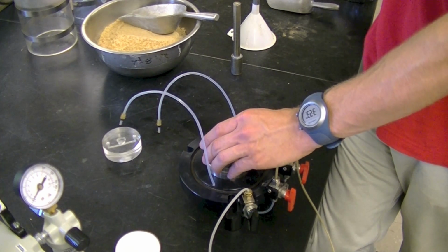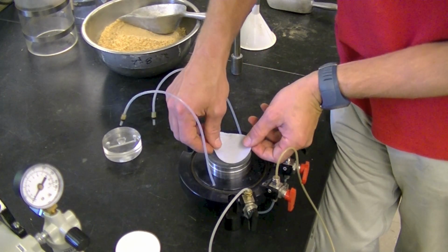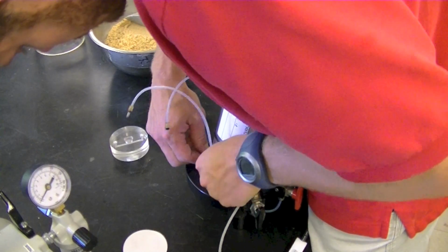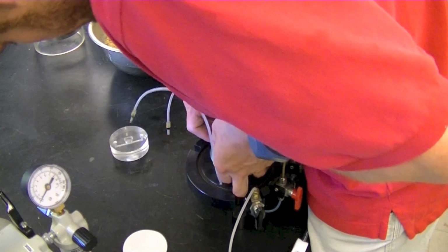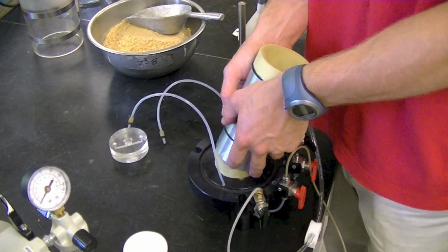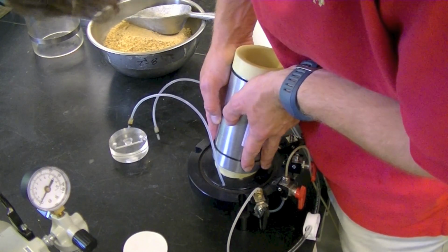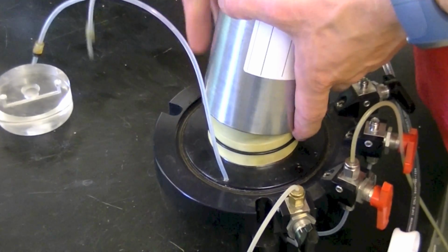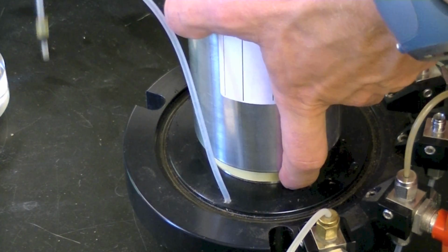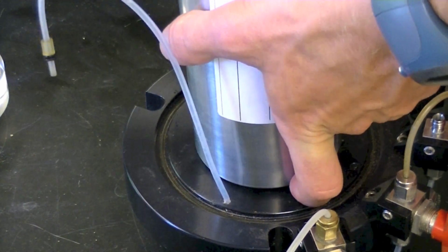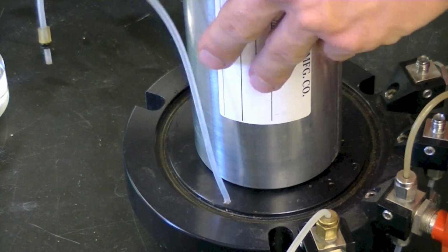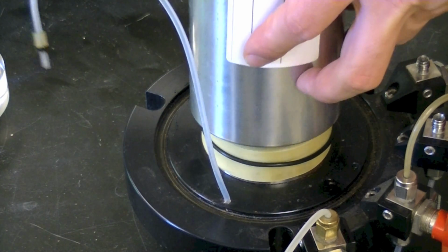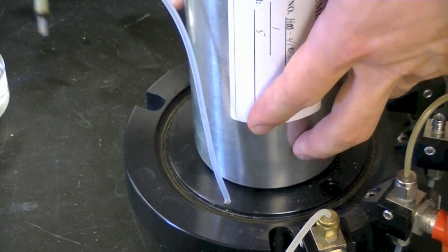After placing a porous stone and filter paper onto the bottom platen of the pedestal, slide the bottom end of the membrane off the mold and onto the platen. Turn the vacuum on to remove any air between the membrane and the mold. Ensure that the membrane covers the whole diameter of the bottom platen. Push the O-ring down into the groove so that it seats itself and holds the bottom of the membrane in place. This way the soil will not come out from within the membrane during molding.